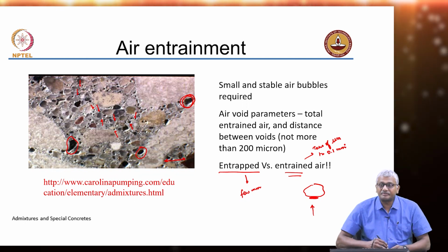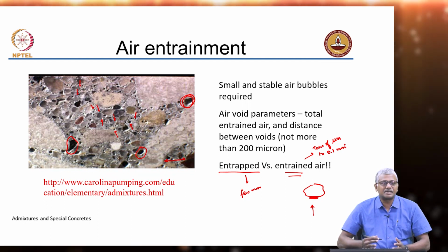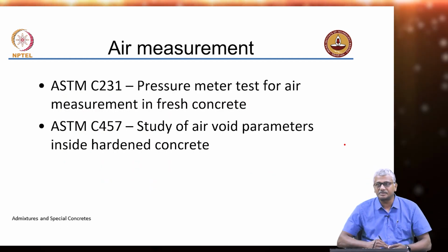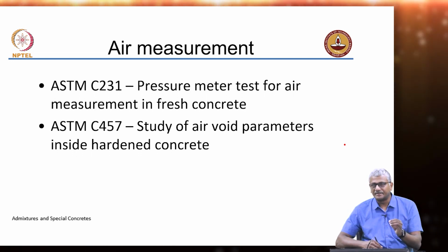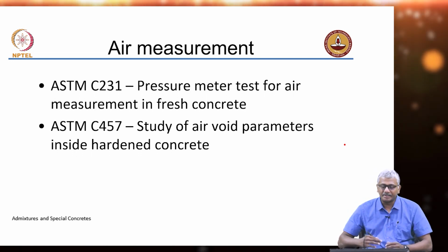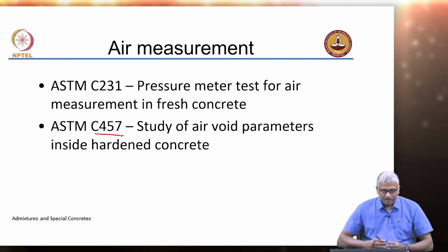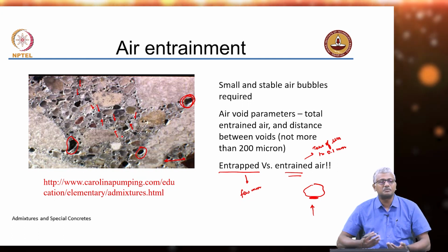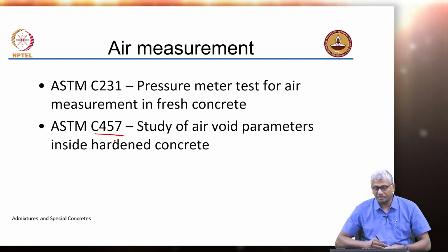C3A and C4AF, as you saw in the pictures earlier with the clinker, are not that easy to distinguish as compared to your C2S and C3S, which are much larger crystalline particles. C3A and C4AF are also crystalline, but they are small enough that they are present almost in an intermixed fashion. In terms of crystalline composition, pure C3A will have a cubic structure, but with impurities it can also get other crystal forms such as orthorhombic.